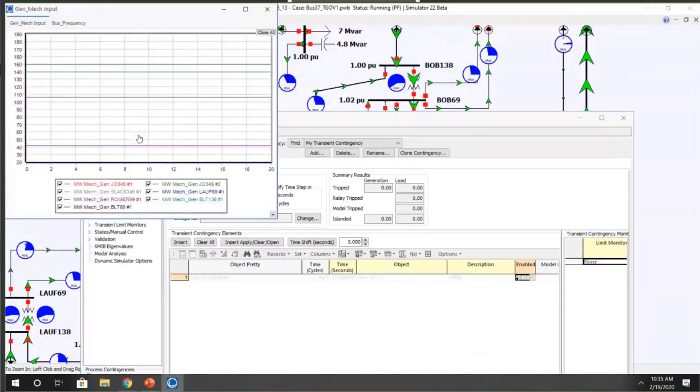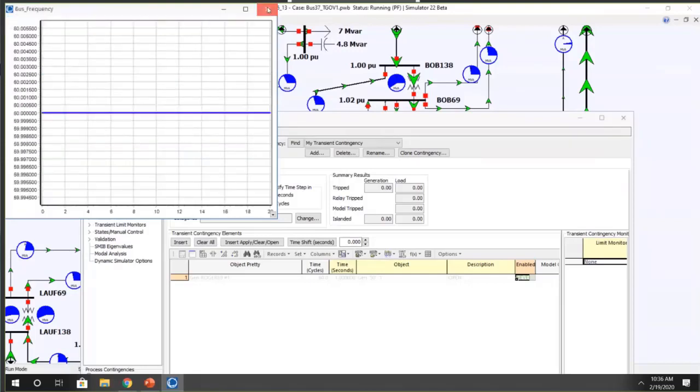Because what we did in the background is we changed that limit to make it so that there was not an initial limit violation. When we went into the initialization code, we looked and we said, hey, that generator is above its limit. The option is set to automatically change the limit. We changed the limit and it was transparent to you. Okay? And that's the default.